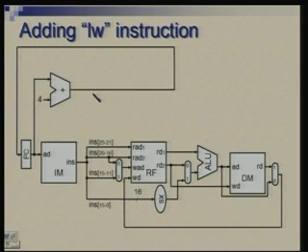You have one instruction, the next instruction follows, but for branch instruction we need to modify this, and also we will use the ALU for equality test. The comparison will be done, and the ALU will produce a bit which will indicate whether the two inputs were equal or unequal.